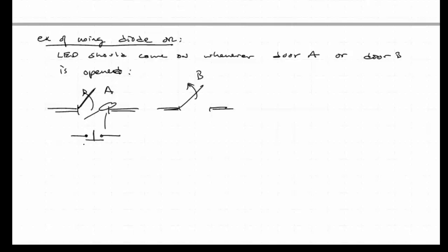So this is a normally closed tactile or momentary switch, but when you apply a force, there's a stem right here, that's the mechanical end of the button. So when nothing's pressed on it, there's a spring that holds it up in contact with the two terminals of the switch, such that current can flow through that switch from one terminal to the other. But when there's an external mechanical force applied to the stem of that momentary switch, the metal contact, which is this bar down here, moves away from the two contact points, and there's an open circuit. So that's the idea here.